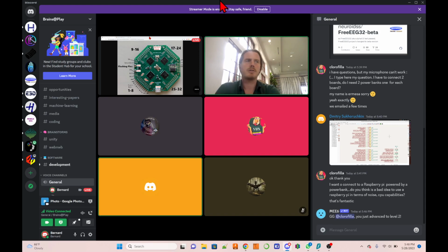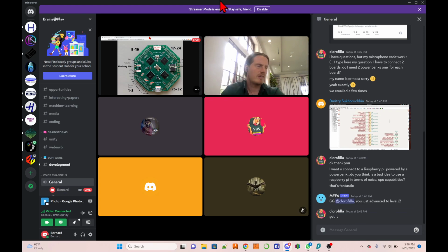Fortunately, with the new firmware, for everyone to know, earlier, until Dimitri fixed it a year and a half, maybe 2 years ago by now, the earlier version of the firmware was using the microcontroller at the full 480 megahertz, and these boards would get really hot.